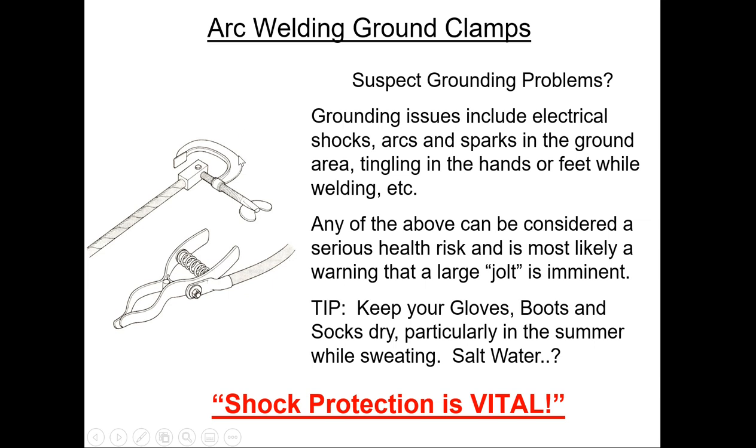And then there's this type of ground clamp that you could be pulling on all day long, and it's not going to do anything, because when you get that electric shock, and I've had a few of them, all your muscles clench. So if you're holding on to the gun and you're using a finger control or something like that, there could be a danger here that you're literally locked on. This, of course, is a serious problem with shielded metal arc welding, stick welding, because as soon as you put the stick in it, it's on, it's live. There's no way to get off of it.